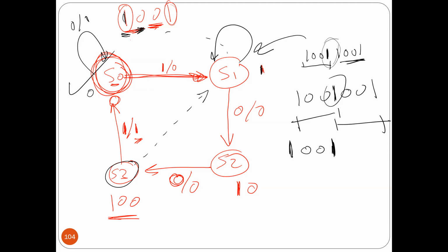So now you have 2 choices. Look here, it's exactly like a programming problem. A little change in the diagram here will make it somehow different, okay? So the way I did it here, once I detect the whole sequence, you have to go back here to get a new sequence. You got what I'm saying? So that means this would be the first case here. Once I get 1, 0, 0, 1, I have to wait for another one to get a new sequence. That's what I did. This one is not going to be overlapped between two sequences.